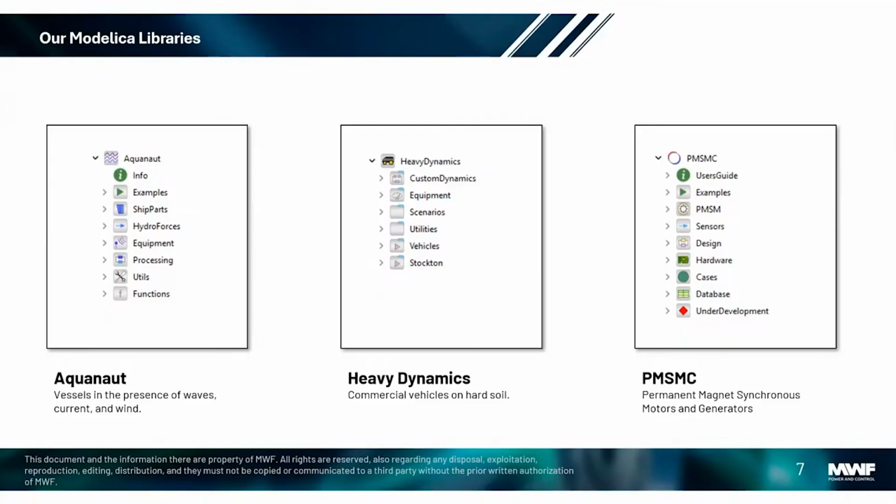This is a library that models accurately PMSM motors and generators and is able to help the designer to design specific control systems, design inverters, check the short period dynamics, and design other types of converters as well, like many different types of rectifiers, inverters, speed drivers, and so on.